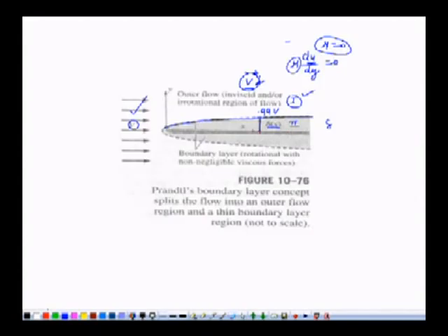So at this section of x, right, what is delta? Delta is a boundary layer thickness at a given section. If we travel in a transverse direction, then velocity varies. Here at delta equal to 0, velocity is 0 to satisfy no slip condition, and as we move upward the velocity increases and it becomes 99% of free stream velocity.